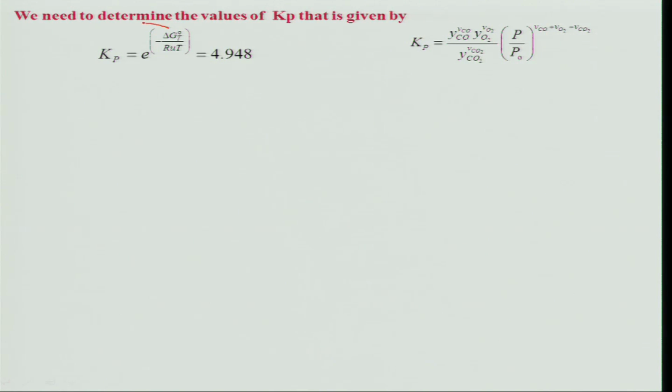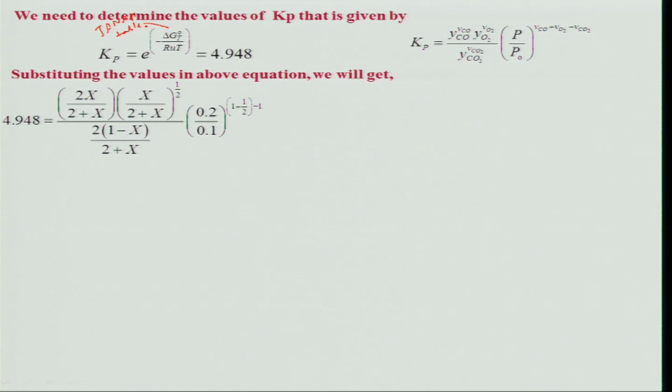If you look at this, I can take from the Janaf table, right, and then I know these values from Janaf, because delta G T I know. If you express that, it will be G, like all those things, and then you will get those from the table. So, these values will be known, and Kp is YCO and all those things we know, and we will substitute this in place of this mole fraction from the table of these values, right, I will get, and then this is known.